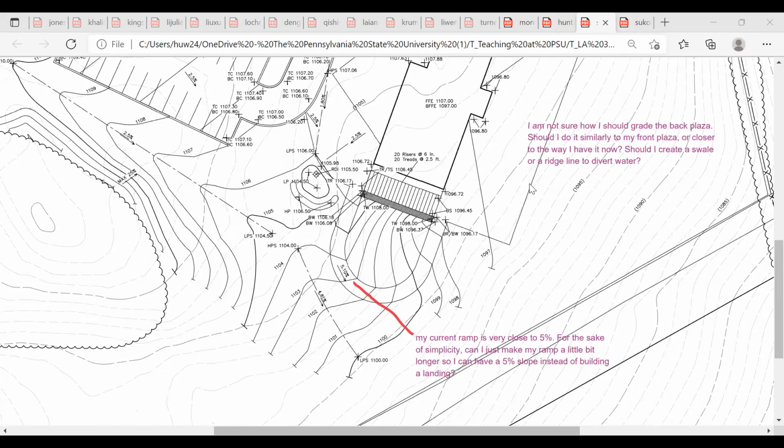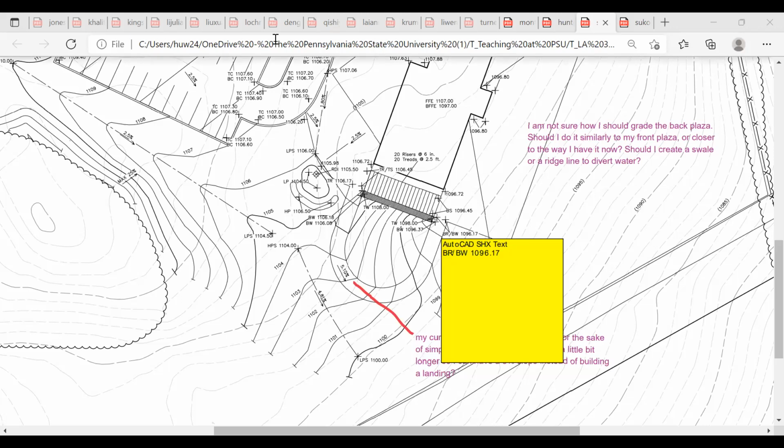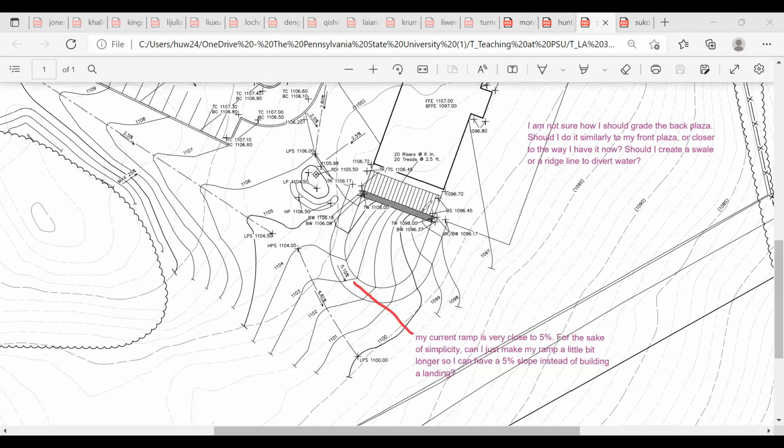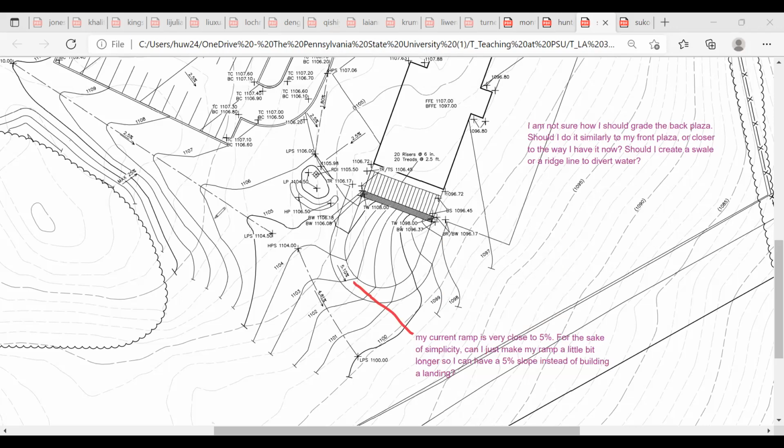Okay. So 4, 3, 2, 1, 0, 8, 9. And there's a wall here. The wall right now looks a little bit off; you would have some concentrations of water in this area. If we change the ramp, well, that's too thick. If we change the ramp like this, we're making it longer, and we may have a better way of connecting the contours. So let's take a look.